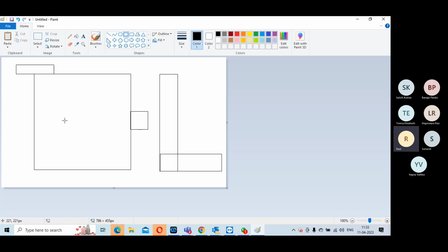This is basically because logic can move, but your macro should not move. Logic can distribute based on congestion. If you put the macro there, the tool has no option to do anything. You have to try and use the memories at this edge. You cannot even place the memories in between. You should try and use these particular ends as much as possible for placing the memory macros, so that the logic can move smoothly to meet your timing. That should be your initial thought process for your floor plan.